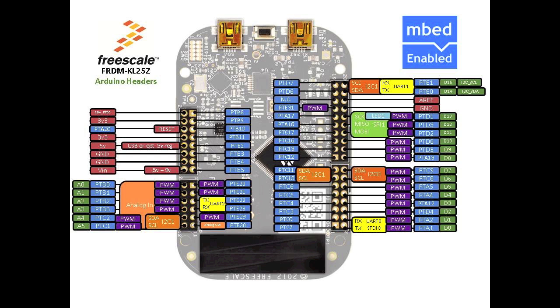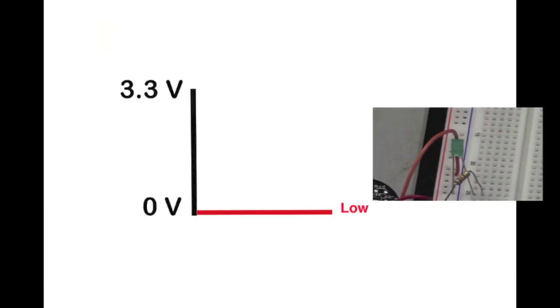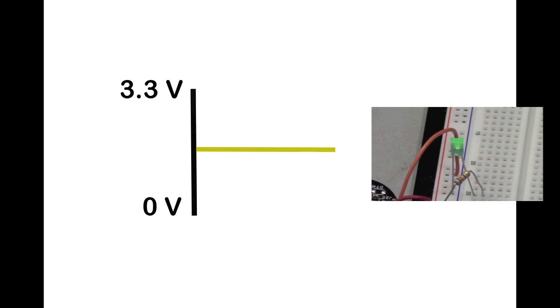Now, this microcontroller does in fact have one digital to analog converter that can generate different voltage outputs between 0 volts and 3.3 volts, but there is another trick you can do with digital pins to create a value that is pseudo-analog. If you flicker the digital pin fast enough, on average, the voltage will be roughly some mid value. Now, you won't get a true analog value, but thankfully with light, your eyes can't pick up anything that flickers faster than 60 Hz. So, if you flicker the LED extremely quickly, the LED will look like it's slightly dim.